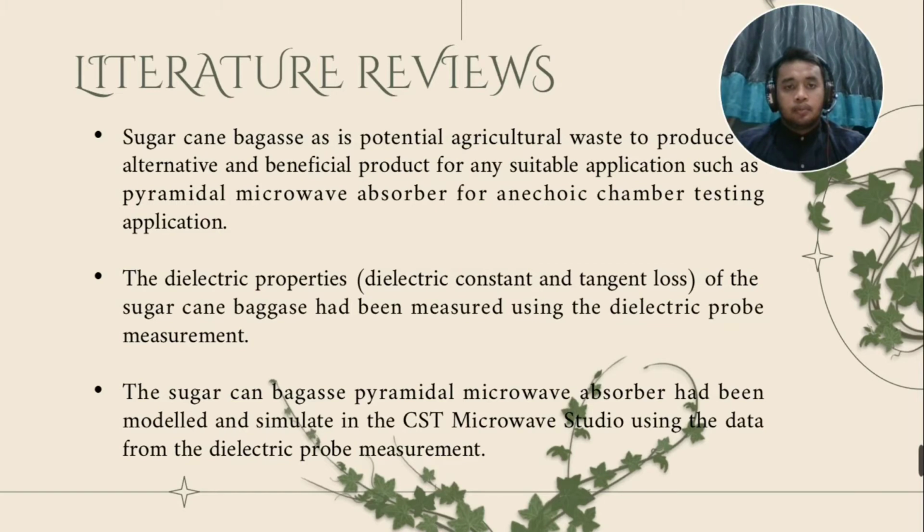The electrical properties they measured are the dielectric constant and loss tangent, using dielectric measurement. Then the sugarcane bagasse pyramidal microwave absorber was modeled and simulated also in CST Microwave Studio, using the data from the dielectric probe measurement.